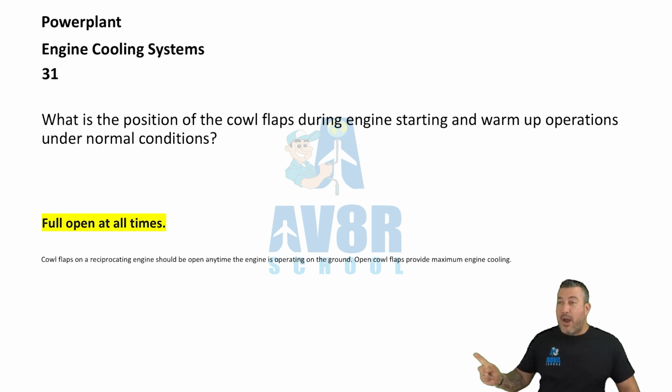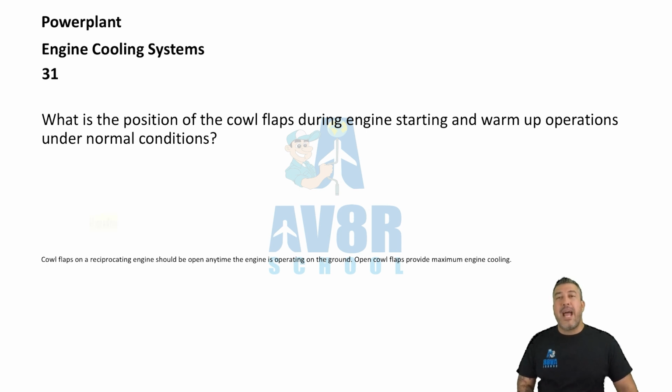We had another question very similar to this, right? It said if you're doing a ground run-up, which position should the cowl flaps be in? Everything needs to be at full open at all times when you're doing an engine startup or warming up.